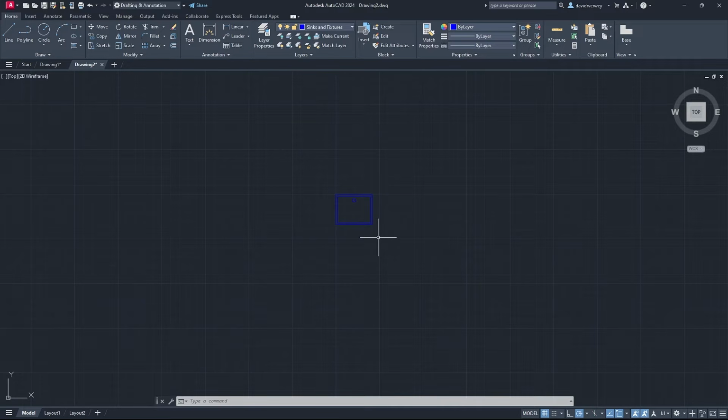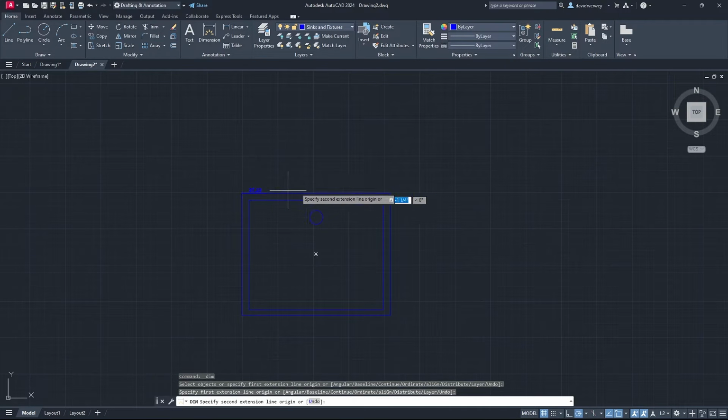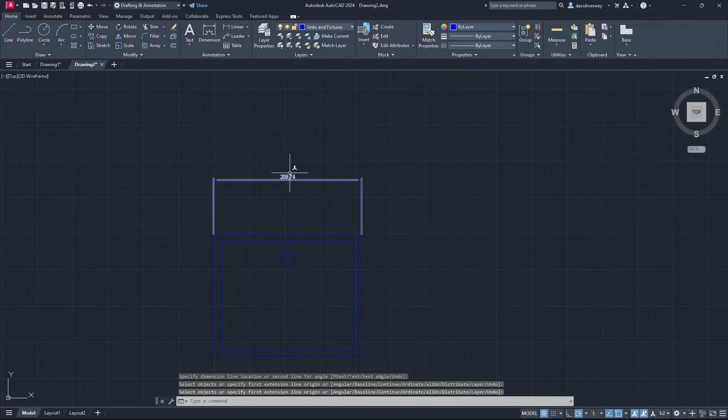So you don't really have to do anything for this video, for this lecture. Just watch the video, listen to the instructions. And then what we're also going to do is use M lines for the main structure, or we're going to use polylines or offsetting, whatever you feel like. Make sure your walls are spaced 4 inches apart. For dimensions, for annotation, make it 1 to 2 when it asks you this. If it asks you that, and you click annotation, click OK, and then we'll be able to use dimensions, and that's it.